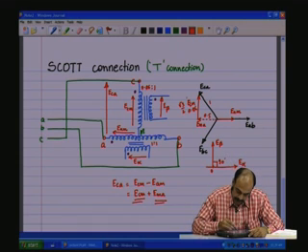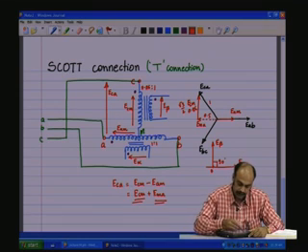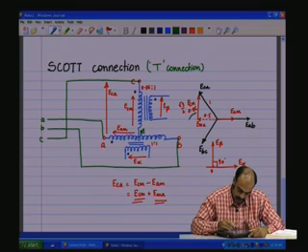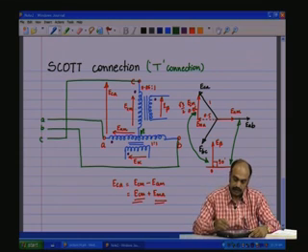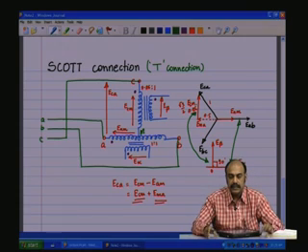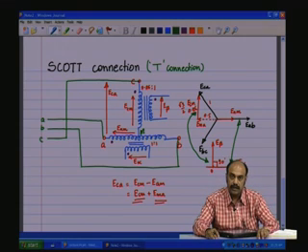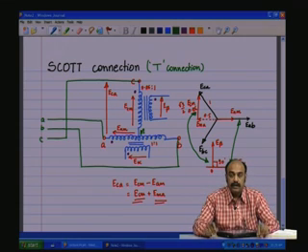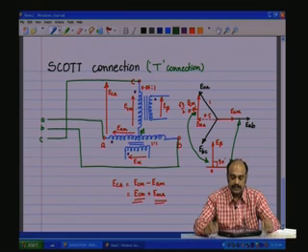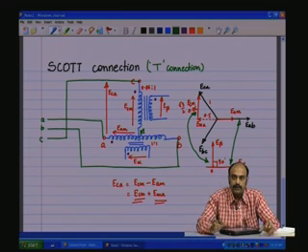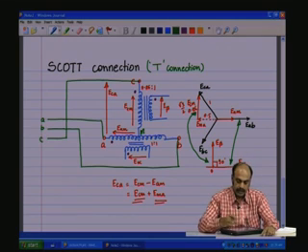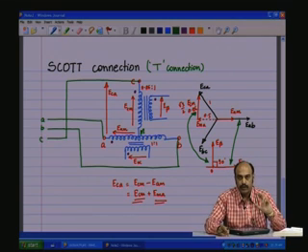You see that ECM is E beta, EAB is E alpha. So, EAB and ECM are phase shifted by 90 degrees with respect to each other, and therefore, they can form a two phase system. Only thing is their amplitude: EAB has a normalized amplitude of 1 and ECM has normalized amplitude of 0.86.